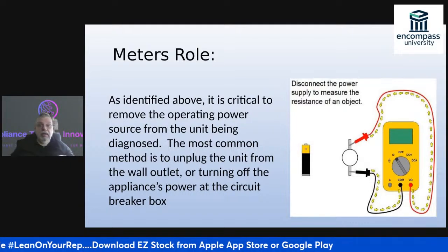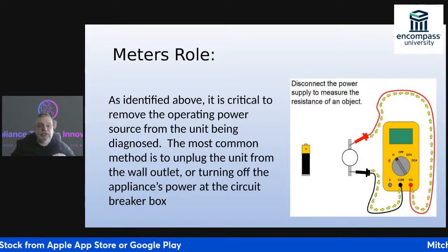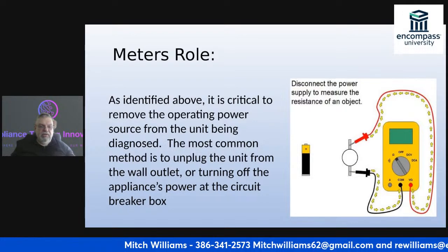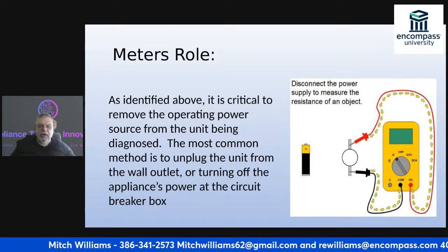If I'm trying to diagnose something, the most common method is to unplug the power outlet, turning the unit off, or turn off the appliance's power at the circuit breaker box.